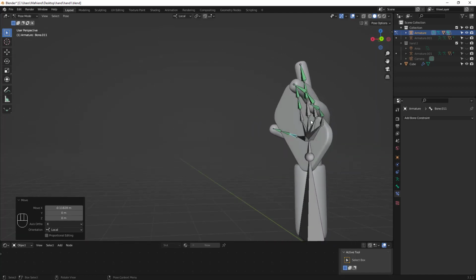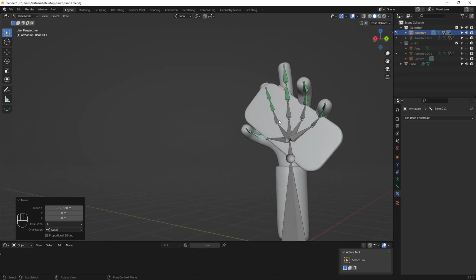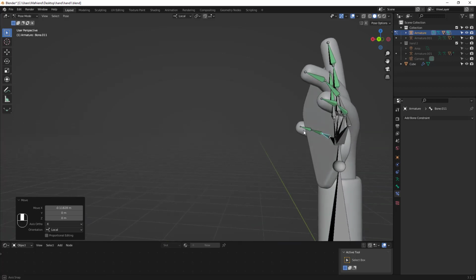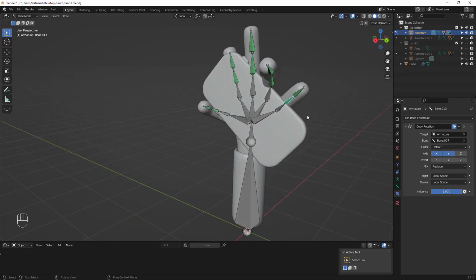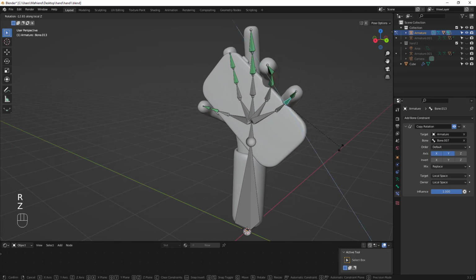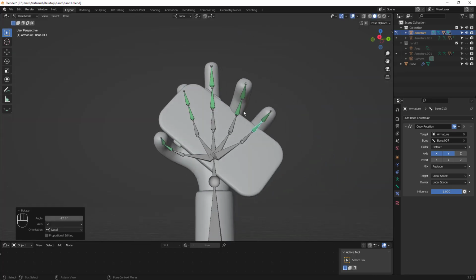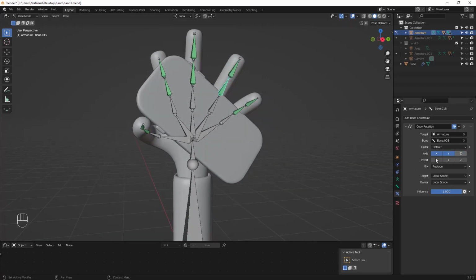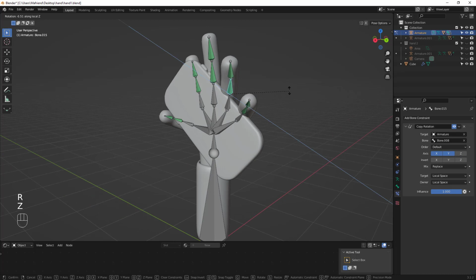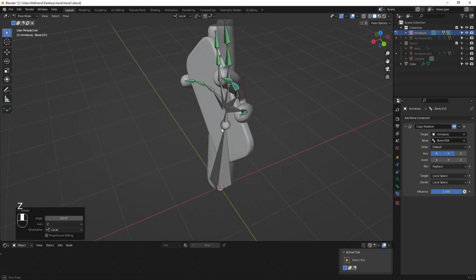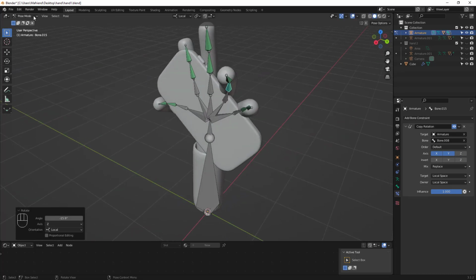so if the rotation is too much and it's cutting inside your phone, as mine is right now, you can select this object here, then you can hide, go and take this axis and it will make it straight, and then you can do R, Z to rotate just this axis, and you can do the same for this one as well. So I'll uncheck to make it straight, and then I'll do R, Z just to rotate on this axis like this.